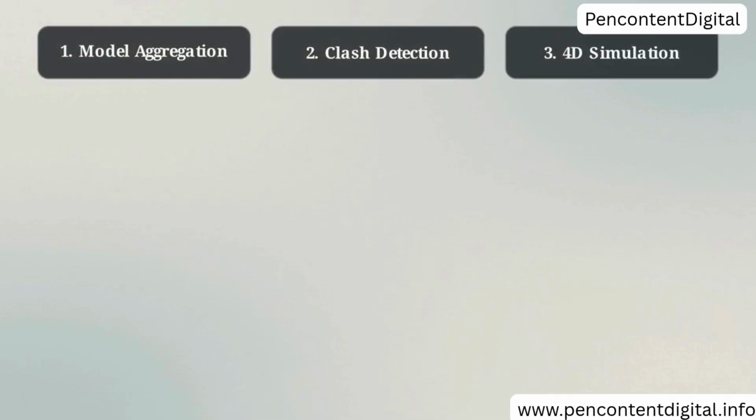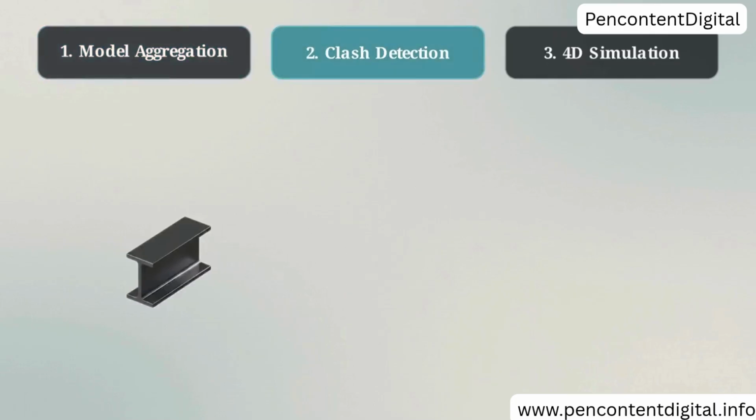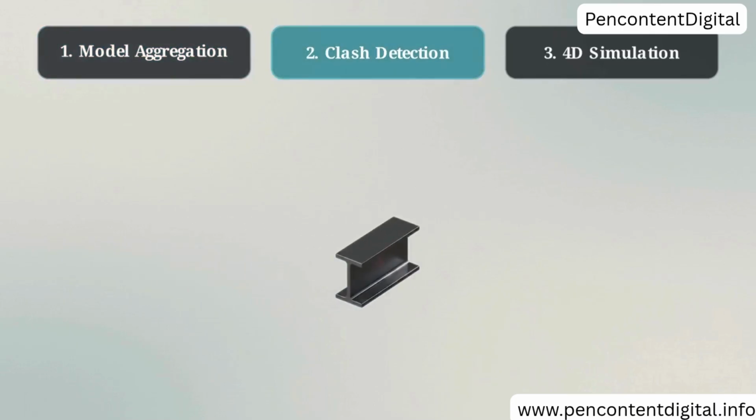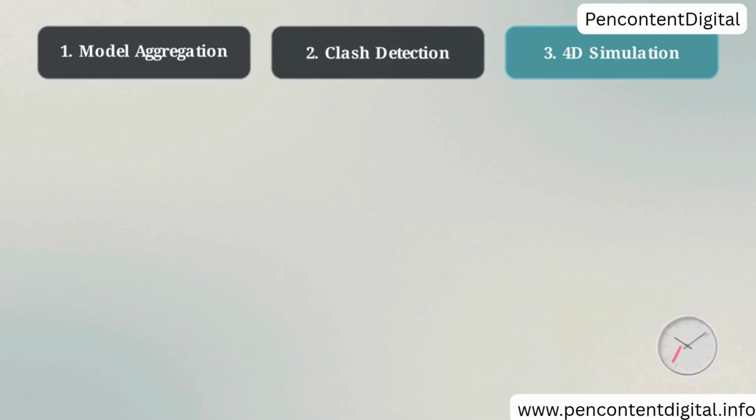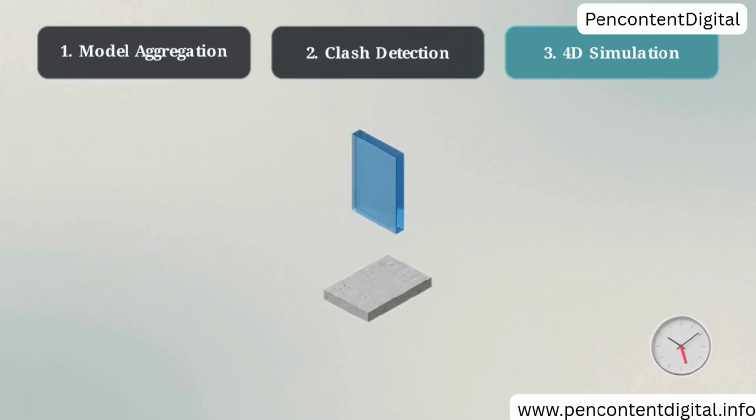This diagram outlines the three-stage pipeline required to reverse engineer a fully coordinated digital twin from scratch. Phase 1 requires merging isolated engineering files into a single comprehensive spatial database. Phase 2 introduces strict spatial constraints, systematically identifying any point where structural systems physically overlap. Phase 3 moves beyond physical geometry by adding time, injecting scheduling data into the structural components.